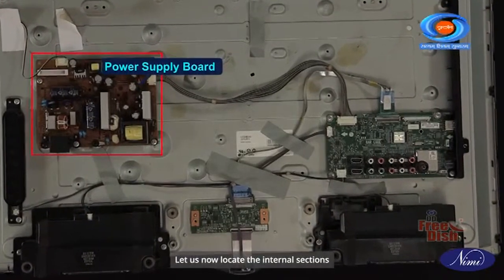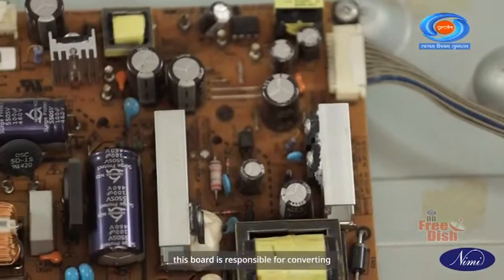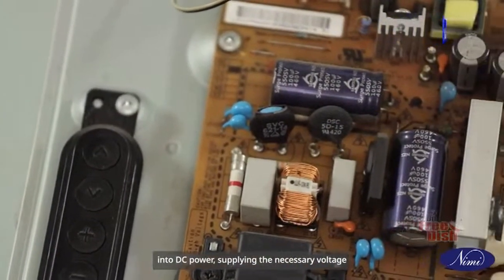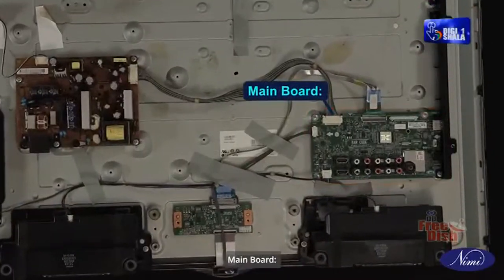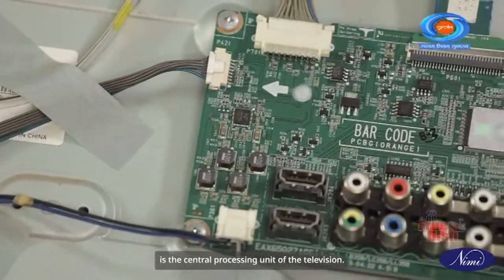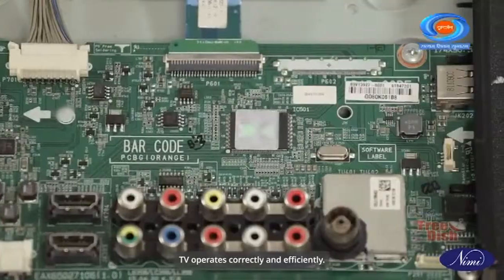Let us now locate the internal sections of the TV. Power supply board. Located towards the lower part of the TV, this board is responsible for converting AC input power from the wall socket into DC power, supplying the necessary voltage and current to the TV's internal components. Main board. Usually found at the center of the TV, the main board, also known as the motherboard, is the central processing unit of the television. It controls audio, video, and user interface functions, ensuring the TV operates correctly and efficiently.